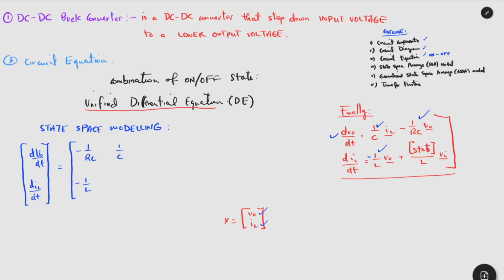So now we have minus 1 on l and v0, and then we have the other state, which is 0 for the off state. And we have now included our state variables, which are the v0 and this il. So this state representation is just the same, where we multiply this one with v0, we get this, and we have this one, 1 on c multiplied by il, we get this equation.